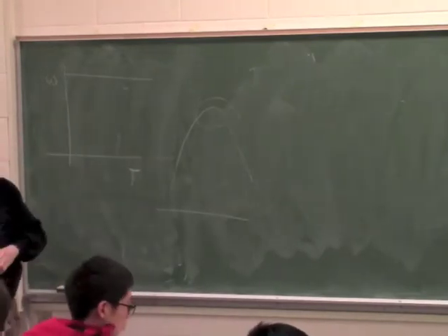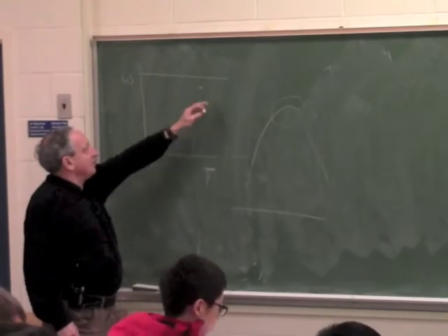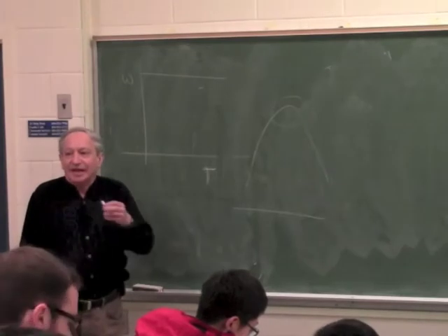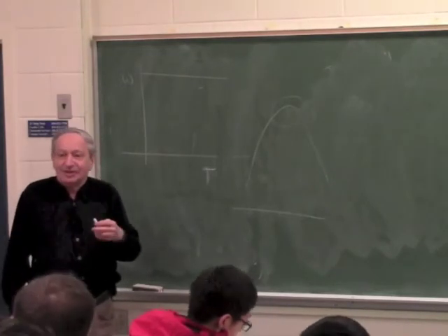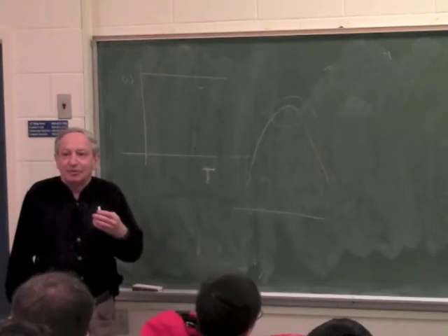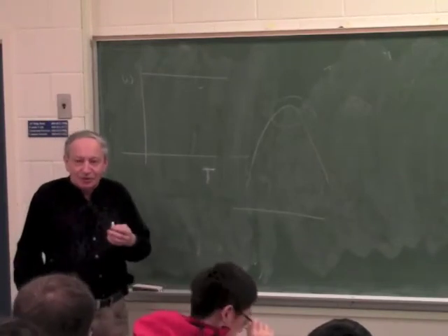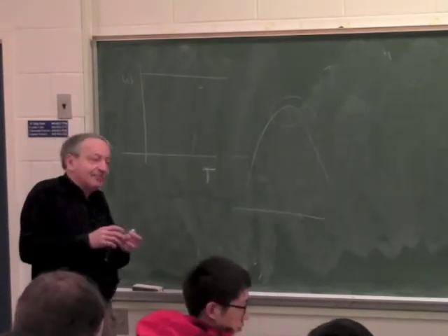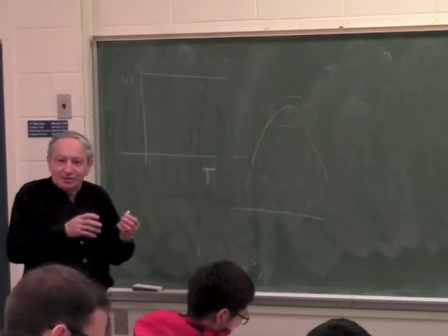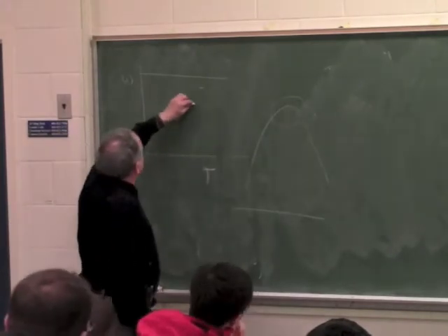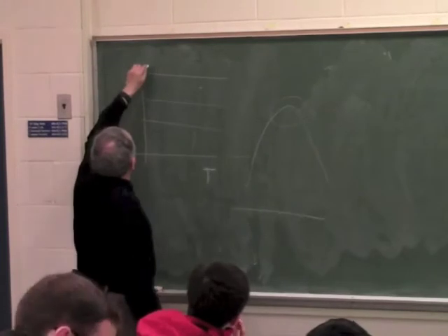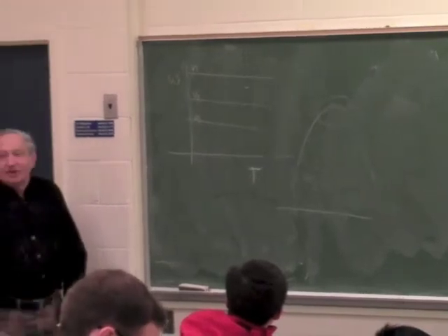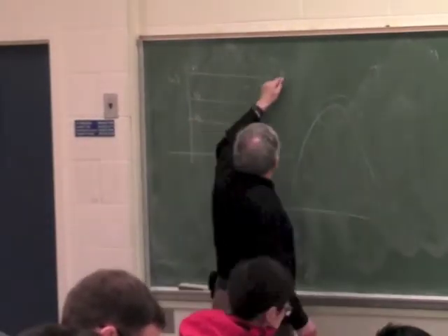PMDC type motors, where the speed dropped a little bit when the torque went up. And the reason the speed dropped, I'm reminding you, is because of the IR drop. Okay, so the more torque, more current, more IR drop. So the actual voltage the armature saw was dropping, so the speed matching a given EMF to match that also dropped. And as you recall, there was a family of curves, and this is V1, V2, V3. As you lower the voltage, the curves drop, and this was PMDC.